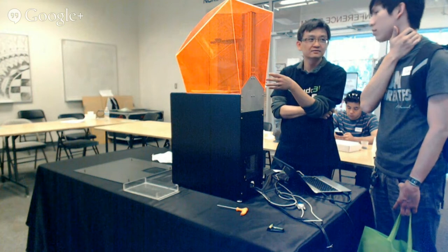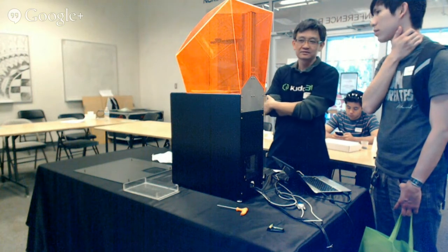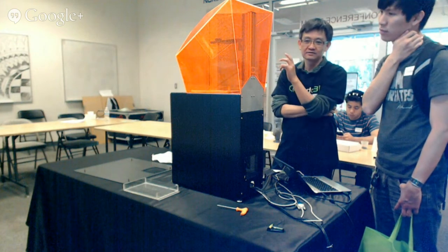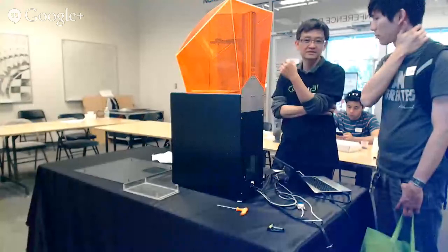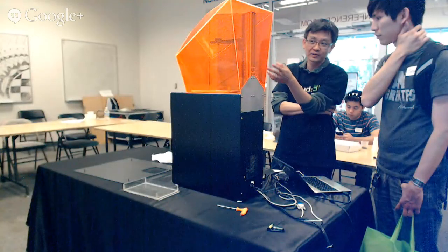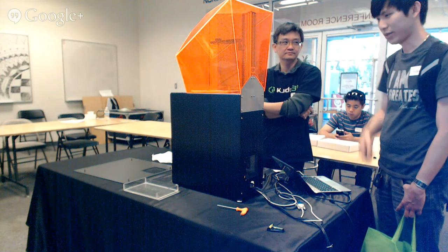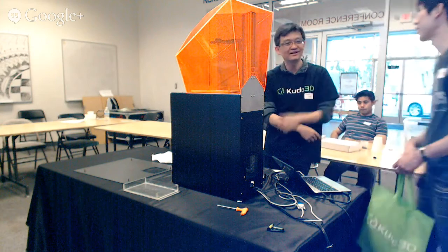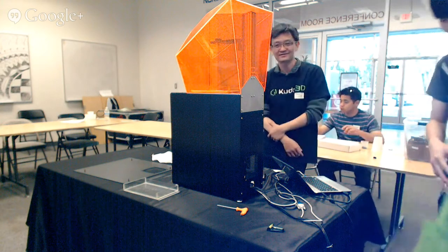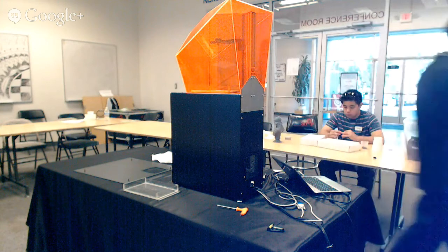The consistency is there, right? Yes, because in the end, it's mostly ABS. It's going to mostly come out the same. But there are the shrinkage factors. If I curve components, if I have issues where I don't take shrinkage into account and I have thick walls joining onto thin walls and all that, it'll still work in the Stratasys stuff. But all of these things will affect you in regular real ABS and a regular 3D printer.